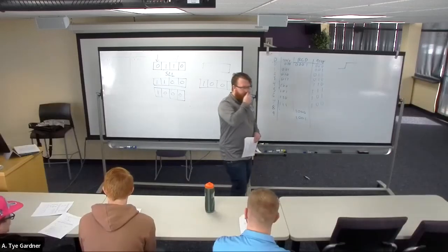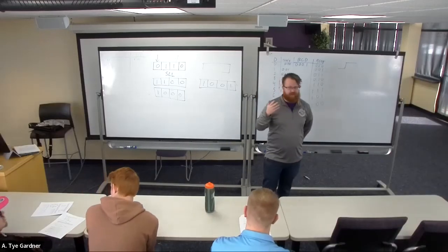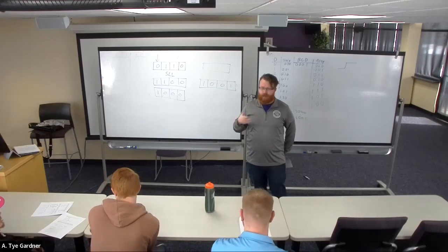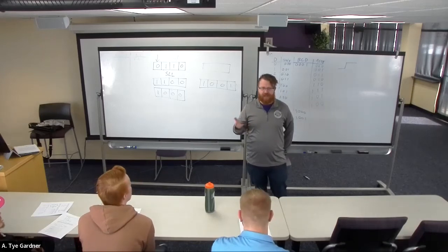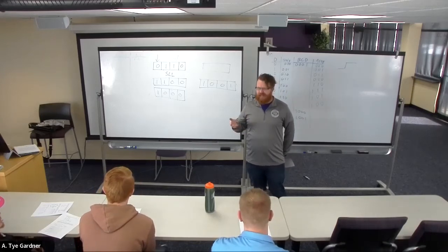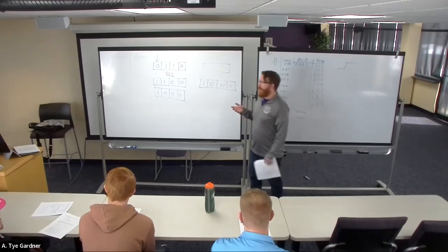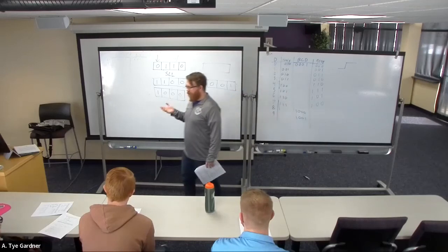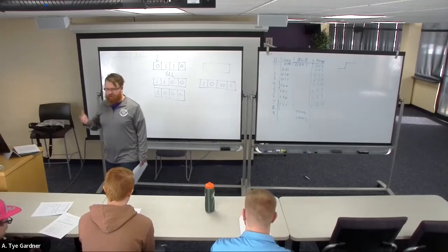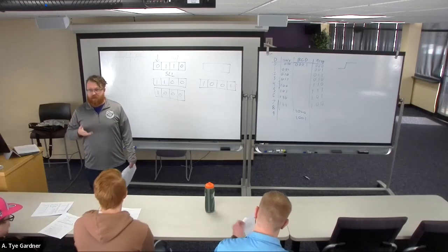Weirdly, most of you that didn't understand priming the circuit and how to stimulate to find a hazard also did the gate timing wrong, which was very odd. If you don't understand the timing diagrams, you may want to talk to me or get some sample problems, or check the homework, something, because they're really important.